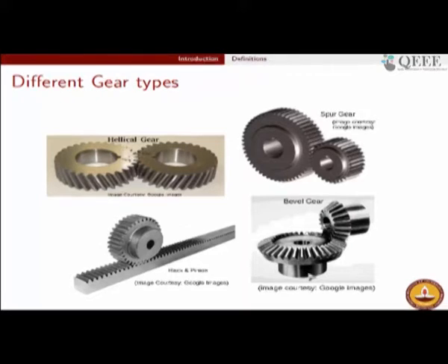So, the shafts, or extended portions of the shafts, would probably be these. As you can see, these shafts are intersecting; they are not parallel as in the case of spur gear. So, this gearing arrangement is called a bevel gear arrangement. Again, bevel gear is something which we will not study in this talk, but if you can understand spur gears, then possibly you can take a more advanced course wherein you can get to know how helical gears and bevel gears are dealt with. So, these are the different types of gears.